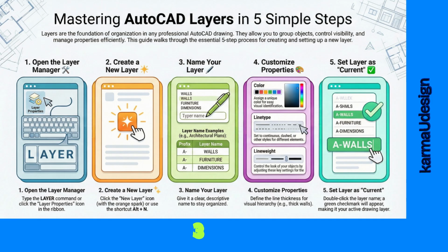Wow, so that raises the technical bar significantly. You're not just naming a wall. No. You're embedding project metadata directly into the layer name. Why does that become so critical when you enter a collaborative workflow? Okay, so in collaboration, your drawing is often externally referenced, or X-refed, into other disciplines' master files. So if my electrical file references your architectural file, I need to be able to instantly turn off all your furniture layers to reduce the visual clutter. Without accidentally turning off something important.